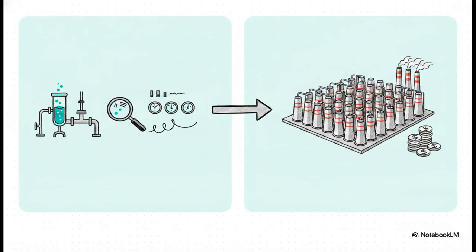So if we can't safely test our theories in a massive factory reactor, what do we do? Well, we use a half-large-scale bridge known as the pilot plant. Pilot plants exist purely for information gathering and verifying mathematical models, which is a stark contrast to factory-scale reactors that have to maintain profitable production. A pilot plant might consist of just one or two full-size tubes of a reactor, rather than the thousands you'd find in the final factory. It's that absolutely critical intermediate step where laboratory-derived kinetics finally meet conditions that resemble industrial reality.